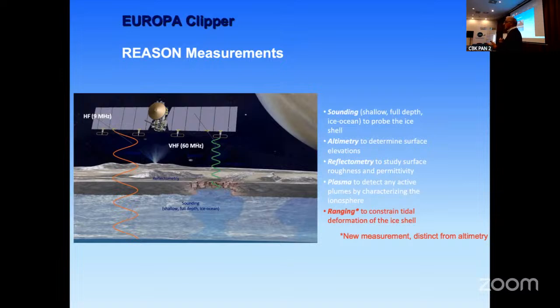And the problem with this sounding radar at 10 megahertz, this kind of thing, is the ionosphere. As I showed you, the ionosphere disperses and perturbs the signal, and we have to correct this. If not, we cannot use the Mars data. For Ganymede, it's a little better because it's higher frequency, but it still needs the corrections, which means that for Earth, a low frequency radar is a problem. But with SAR radar, you can operate all the time.